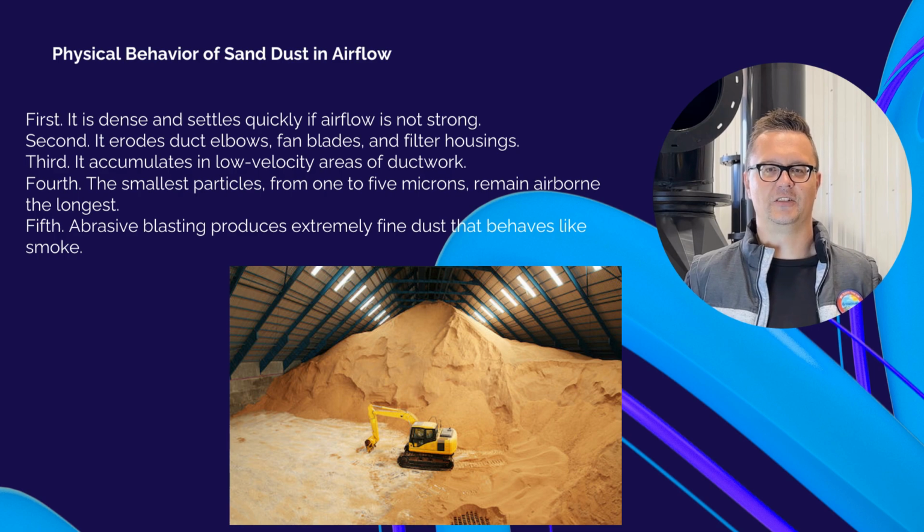Physical behavior of sand dust in airflow. From an engineering perspective, sand dust behaves differently from organic or polymer dust. First, it is dense and settles quickly if airflow is not strong. Second, it erodes duct elbows, fan blades, and filter housings. Third, it accumulates in low-velocity areas of ductwork. Fourth, the smallest particles, from 1 to 5 microns, remain airborne the longest. Fifth, abrasive blasting produces extremely fine dust that behaves like smoke. To keep sand moving and prevent buildup, I design duct velocities from 4,000 to 5,000 feet per minute.